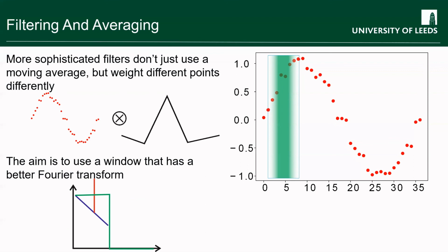Now, of course, the issue is that you can't really get quite such a nice abrupt shutdown, but there are different types of signal filtering options, and these can be implemented in hardware or in software, that will give a nice frequency response and not reintroduce unwanted frequencies into your measurement. In software, you can always have a look at, for example in Python, the scipy.signal module, which has a whole slew of different functions.